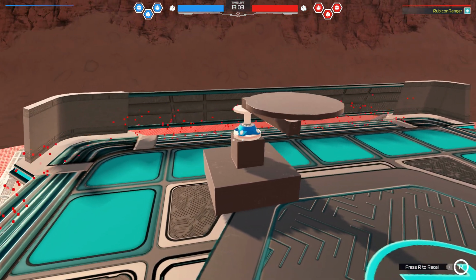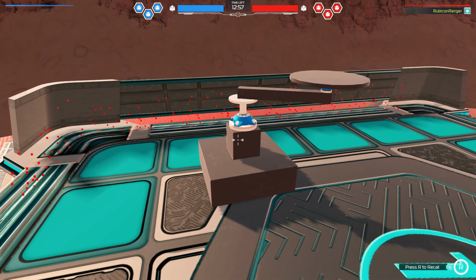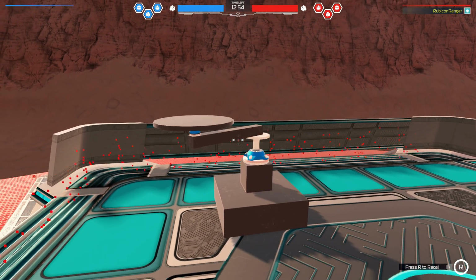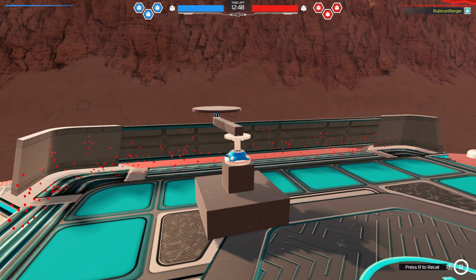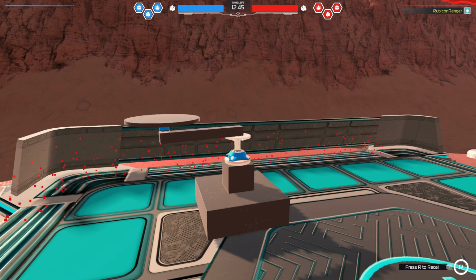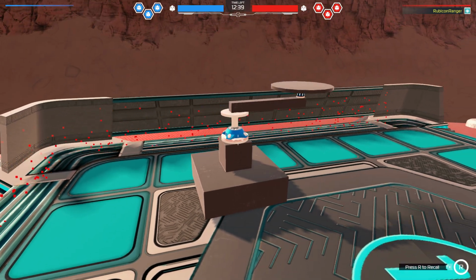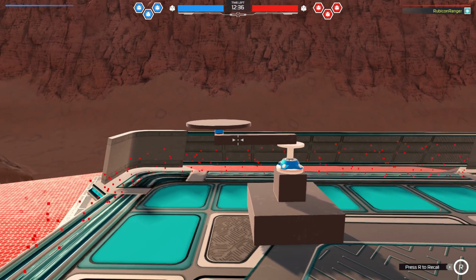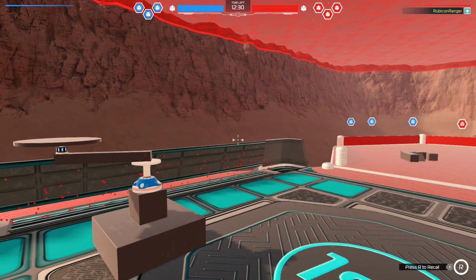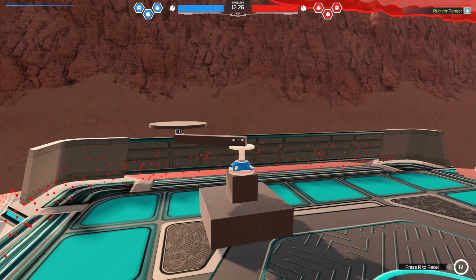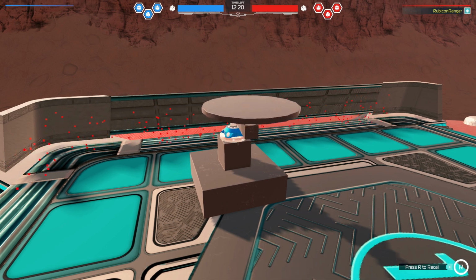And then finally we have our good old-fashioned gyroscope here, and you can see, like I was talking about, if we spin the plate one way, it makes the arm spin the other way, and then it spins the same direction around the hinge which is holding it. So all that cancels out and goes to ground, versus where your torque is really being canceled out. Now if you're in the air, you'd probably rotate around whatever the center mass of this arm is, if you didn't have this assembly here, right? So if I have 2 of these on either end of a bot and they're rotating the same direction, it's going to rotate about the center point between the 2. You can see that going there. And once again, this is omnidirectional, or bidirectional.